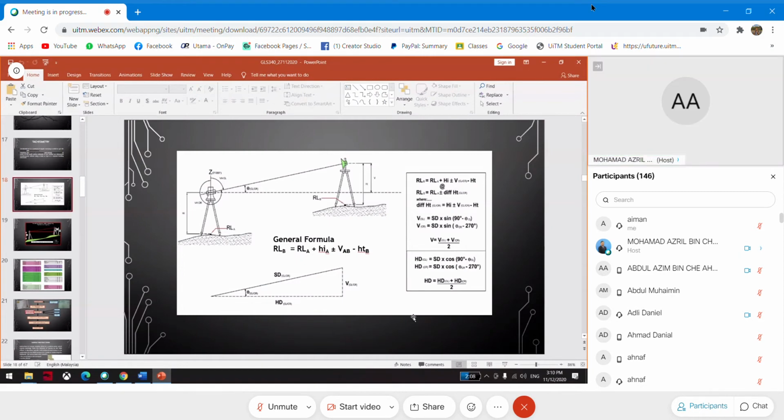When you go to industry, sometimes you will have an approach to use GPS to transfer the elevation. In UiTM, students apply leveling. From the benchmark, transfer to the TBM, and then go back to any known point, as a benchmark or SBM, to close the leveling work.